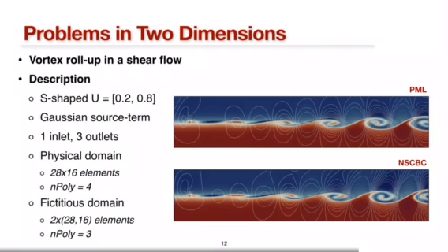What you're seeing is density, with pressure contours added on top of it. Throughout this period of simulation, both boundary conditions managed to mitigate most reflections. However, the characteristic treatment, as opposed to the PML, did not convect the vortices at the proper speed. This is evident from the pressure contour peaks and later confirmed when compared with the reference solution, taken from an extended domain using the same spatial resolution.